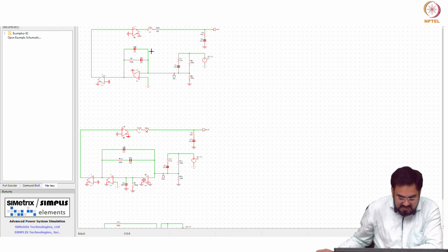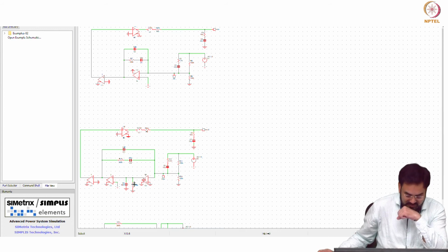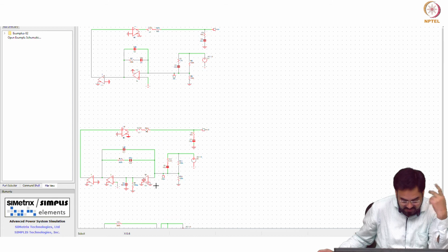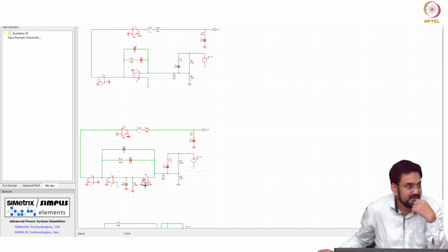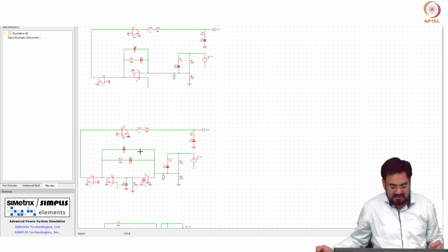So what I did, this was my original circuit, and I replaced this op amp with the first order model. So you have a voltage controlled current source, then I have RC at the output. So GmR will be your gain. I am keeping 1 milli and 1 mega, so it's a 60 dB gain, and the same 1K here. So I try to keep the same, and then you have a buffer to make sure this 1 mega ohm is not loaded with that at high frequency.